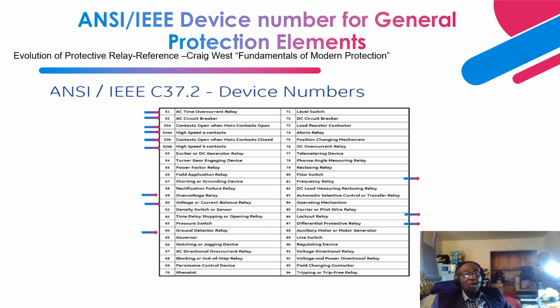So the lockout relay also has a multiplying contact, multiple contacts, that trip other elements. Let's say you have a differential protection that sets in, right? It basically activates. Then that differential relay is wired to a lockout relay, right? So the lockout relay has a lot of contacts. It trips the unit breaker.